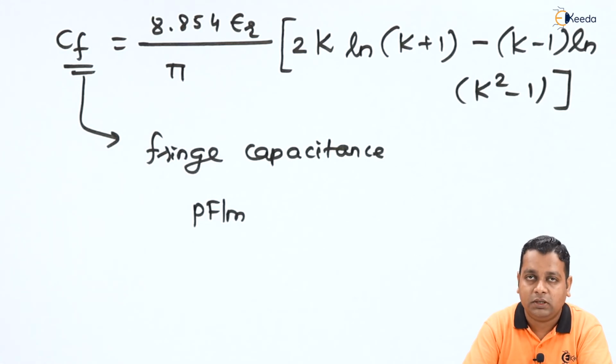So these are the two formulae for the characteristic impedance, which require the value of the fringe capacitance along with the dimensions. We shall be using both of these formulas in the next lecture to compute the characteristic impedance of the shielded strip line. Here we conclude this chapter on transmission with strip lines as the transmission line, and in the next lecture we shall see the various resonance conditions possible for microwave signals, either with cavity resonators or with the help of lumped elements.